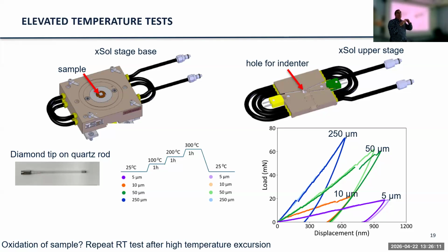We wanted to test, was there oxidation of the magnesium? Because clearly if I had an oxide film and I tried to indent, that would affect things. And you can see that there's almost no difference. This 250, there's really no difference of the heating cycle. So the protective gas has worked quite well. There'll always be some very thin oxide on the material, but it didn't grow excessively, or it didn't affect our measurements during the test.